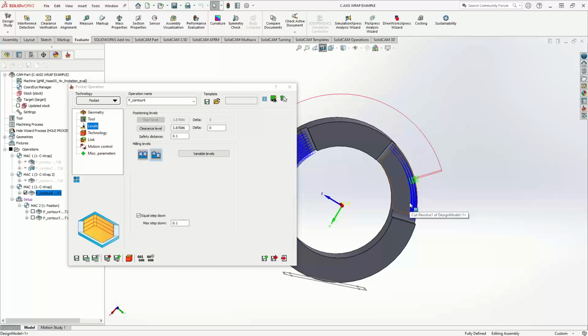So pocket recognition, because it's solid based, essentially you're generating pocketing toolpaths, but because it's a solid-based toolpath, there's nothing about that that can lend itself to being wrapped. And at this point, I don't know if we have a wrapped or rotary solid-based one other than the rotary machining, the screw machining, or just general 5-axis simultaneous toolpath. So we do have something, but it doesn't work exactly the same way. There's a little more depth control in those than this one and so forth.